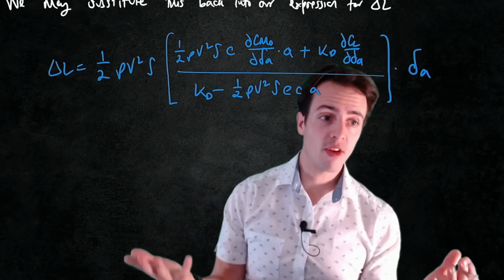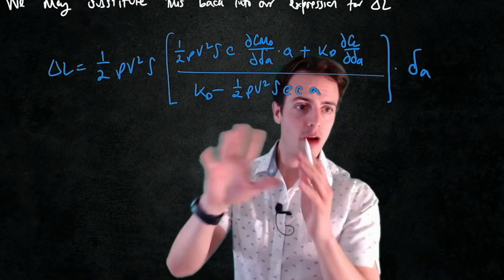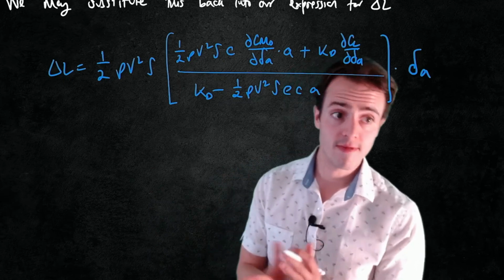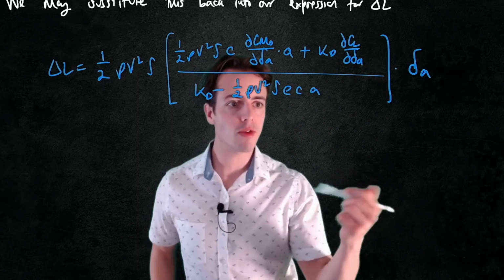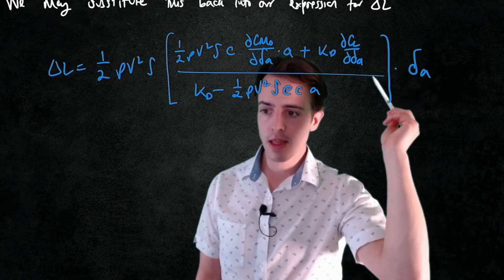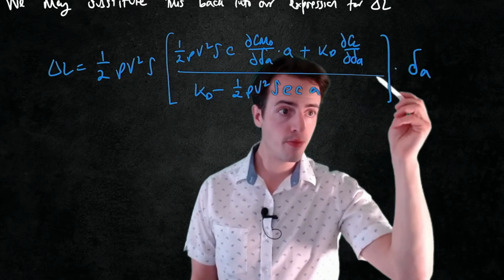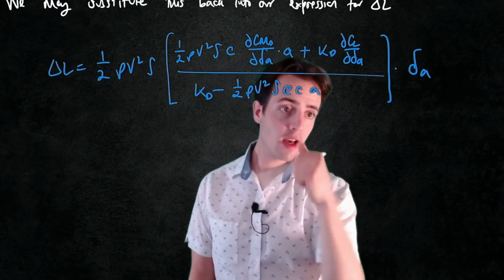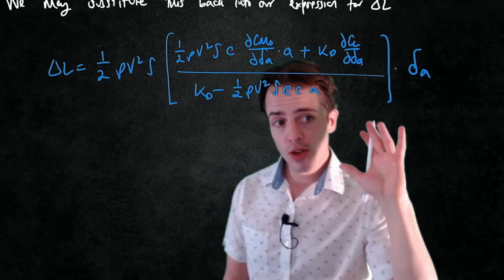So at that point we've got divergence anyway, so we don't care about what happens to the delta L, because that's just the case where we've got lift tending towards infinity, which clearly we don't really have, but shows us when divergence happens. We can also have the numerator be 0. So when the numerator is 0, that's when we have aileron control reversal.